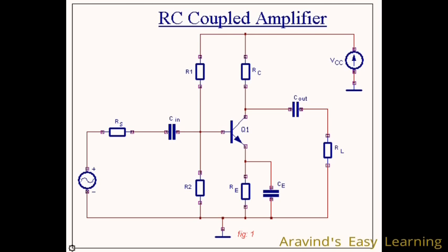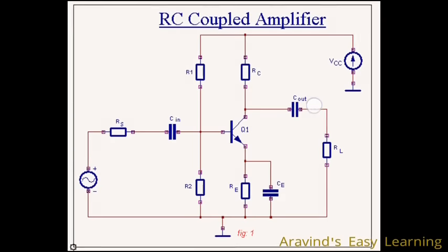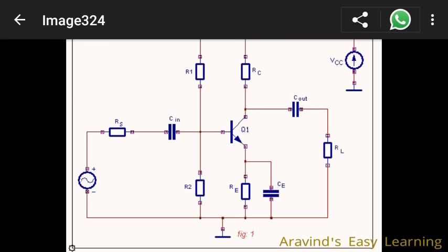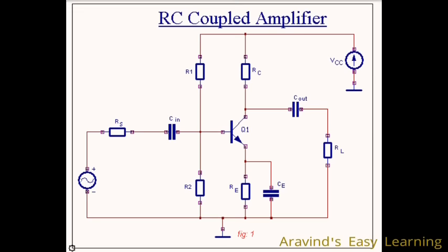Another factor that we consider at high frequencies is the shunting effect. You see, at higher frequencies, these capacitors act as short circuit, no problem. But this short circuit action is so strong that the next stage resistors will come in parallel with these two resistors, and this shunting effect can actually reduce the gain.